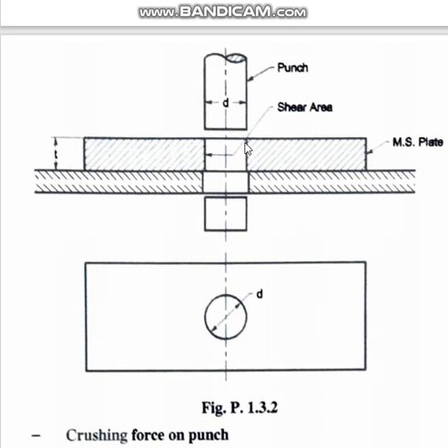The second thing is, if this punch is very hard and this is soft, then if you just pierce or punch through it, because this is softer material, this much portion will just cut and fall off. So what is that property in which this should be weak for this hole to be formed? This piece is actually cylindrical. In front view you are seeing it as a rectangle, but in top view it will look like a circle like this. This falling off piece.